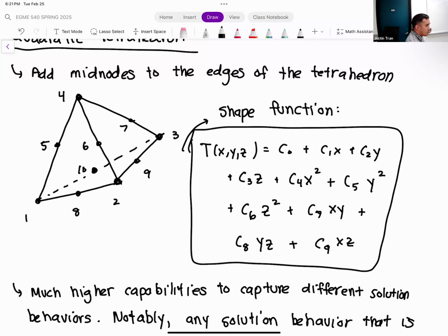And so one thing I actually forgot, someone mentioned it right before we left last Thursday, is that you can actually check the quality of your mesh. You can ask ANSYS how many of your elements are this good, nice, equilateral shape, and how many are very skewed. Because that ratio of skewed elements can also be a predictor of mesh quality. So remind me to show everyone how to do that on activity 4, because it is a very useful thing, and one thing you can use for your project as well. Yeah, absolutely not. So these elements can be squished and stretched.